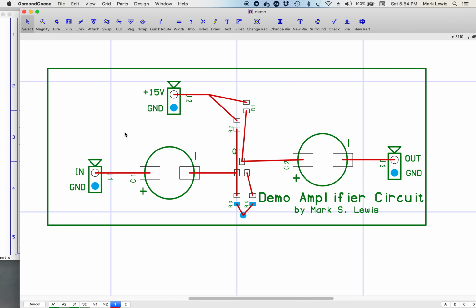Now, when you start getting to multi-layer boards that are like 4 or 6 layers, the price goes up. You might go from $2 to $8 to like $60, or depending upon the size of the board, the price also is going to jump exponentially. So you might design a board that's maybe twice as wide as this and has 6 layers. Instead of paying $2 or $4 for this board, you might end up paying $60 or something like that. And then if you get even bigger, you might end up paying like a hundred and something for it.